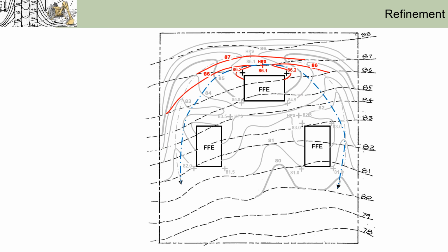And then, when you look at the draft contours, you'll see that most of them are now on the uphill side of their original contours, right? That means we're cutting a lot. The newer elevations are lower than the original elevations. We're cutting a lot. So we need to overall bring the elevations up to reduce that cut.